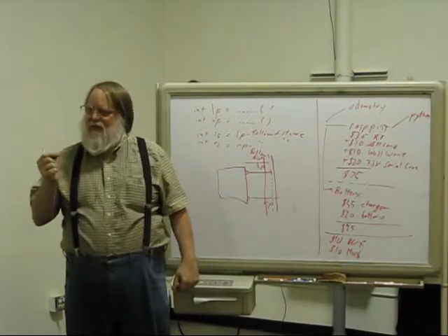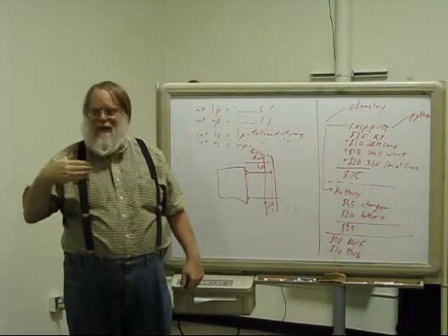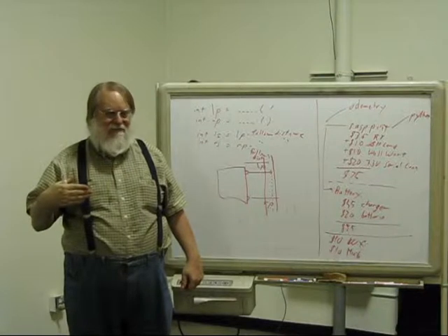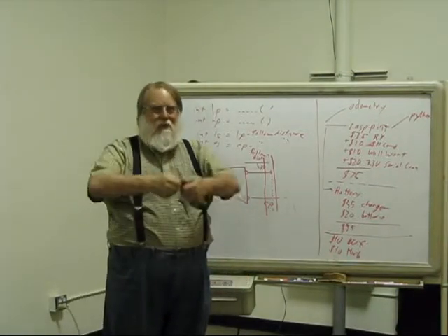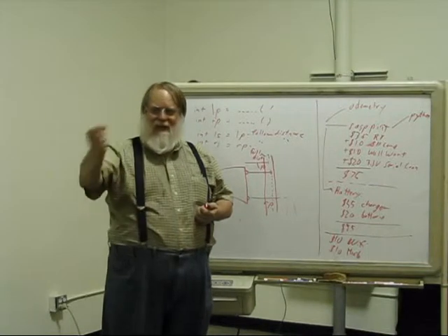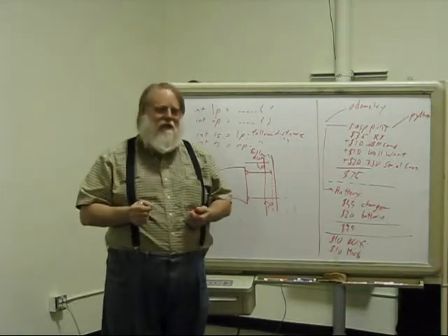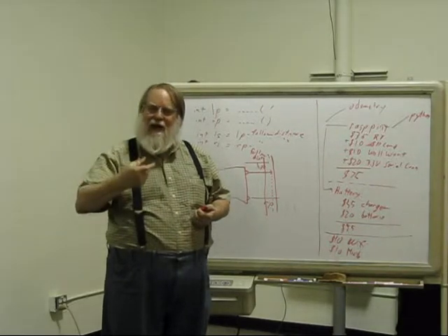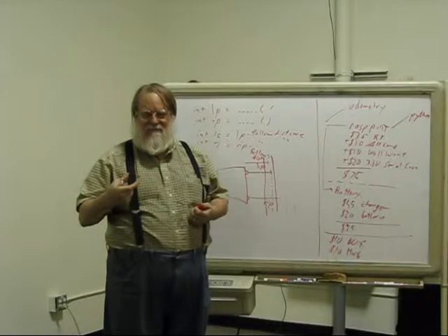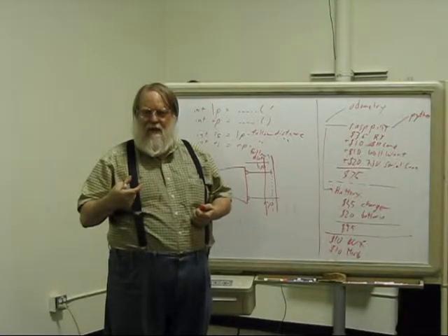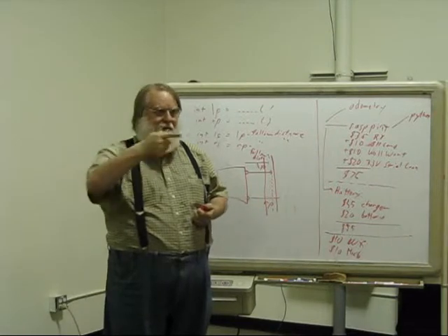The problem with Wi-Fi is it takes a lot of power, and the Raspberry Pi can't provide that much power. So what we do is we take a powered hub, we open it up, and we add a wire, and slip a wire here and there, so that we're basically taking the power from the battery directly as opposed to through the Raspberry Pi.